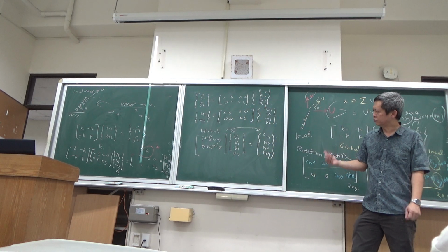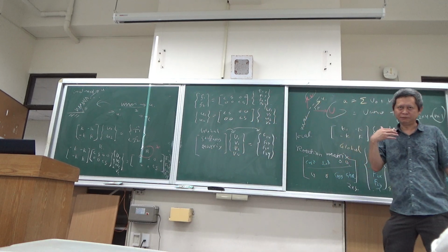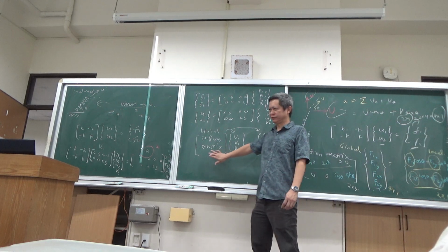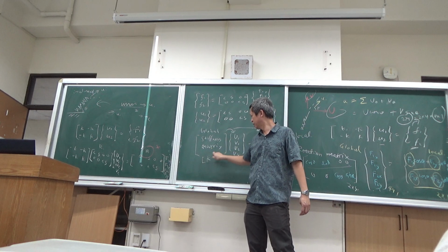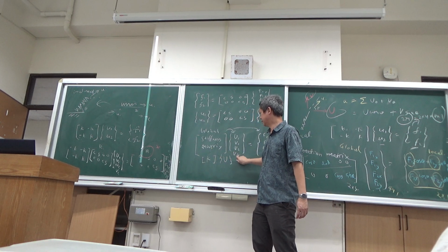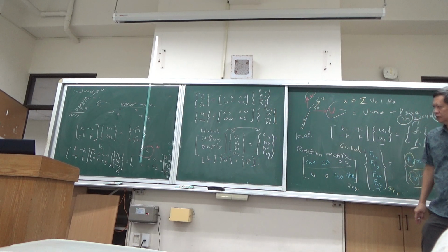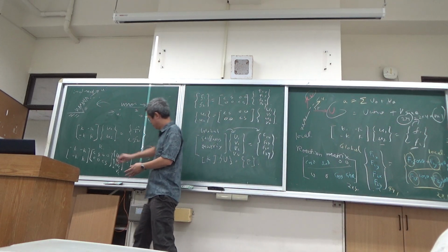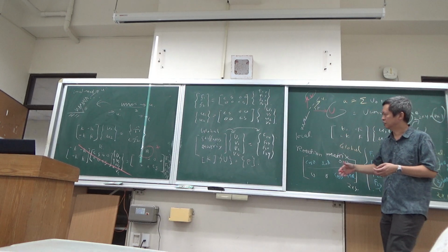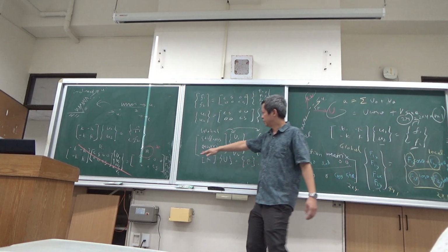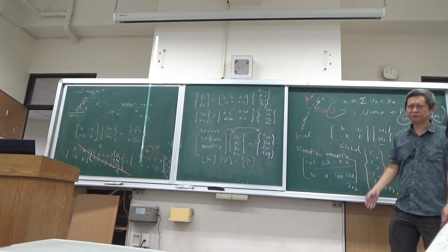Why do we want to write this? Yeah, this bears more physical meaning. If you read the equations, according to Hooke's law, stiffness matrix times displacement vector is equal to the force vector. Okay? So this is not the one we want. You have made the first attempt writing them in terms of the global forces, but the rotation matrix here is simply making the thing bear no physical meaning. Okay?